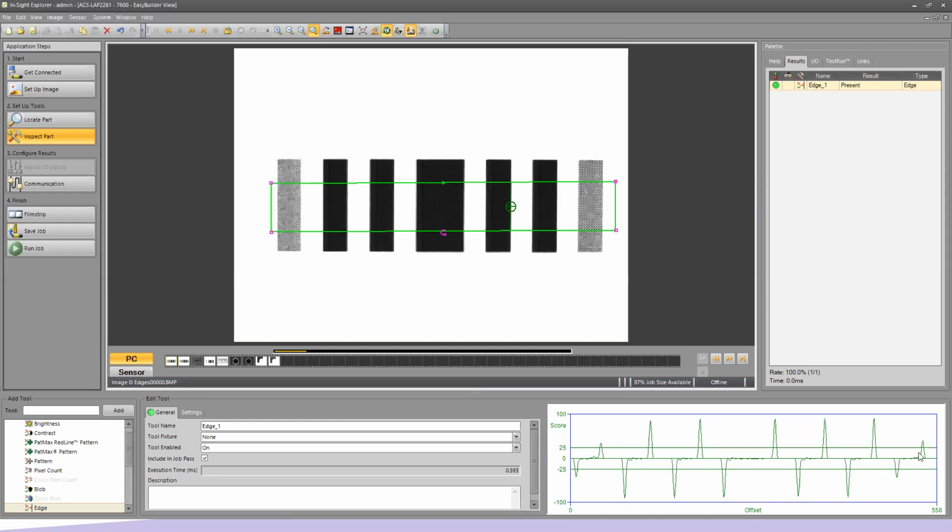The black bars are the taller ones. These are showing the difference in contrast. Contrast is the difference in color from the part to the background in this case. The bigger the contrast, the higher the spike. So we're going to use that to our favor on how we choose what we want to select.